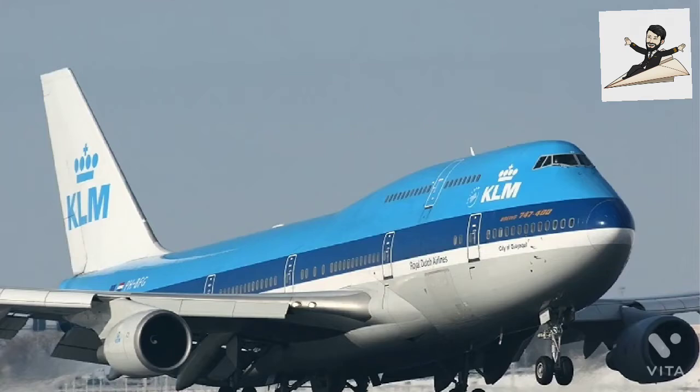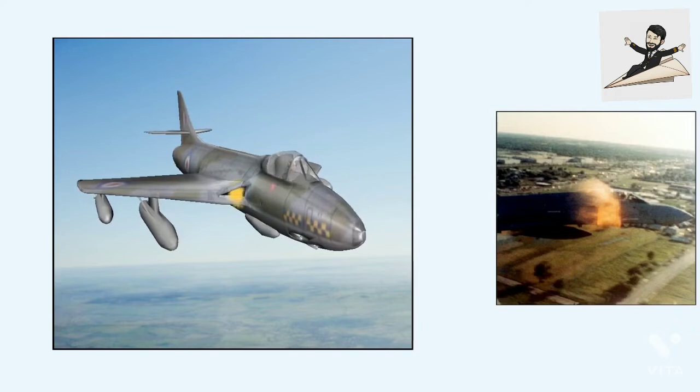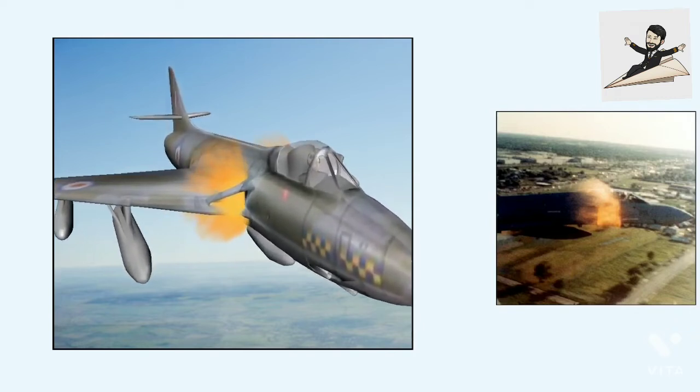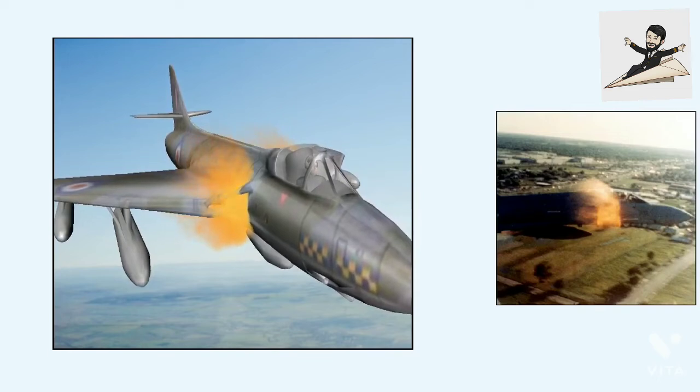So, engine operation below the maximum power level means that we are committed to altering the rotational speed of the compressor, and also the axial velocity of the air as it passes through the engine. Unfortunately, by doing either of these, we are encouraging the onset of stall and surge. Systems that ensure that surge and stall do not happen have to be fitted to the engine. Here are some of those systems.